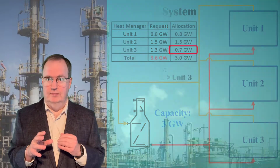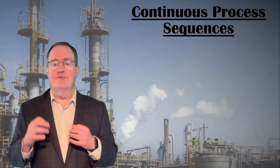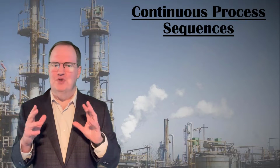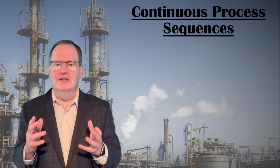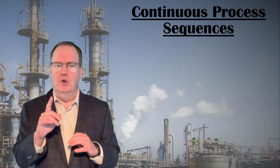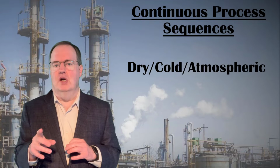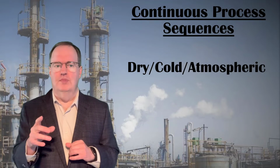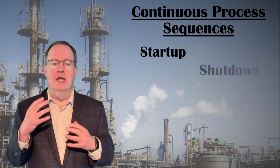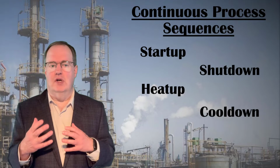The next area where sequential logic is very important is for continuous processes. But you may be saying, continuous processes don't have sequences, they maintain one state in time. Which is true, but only when they're already operating. Every piece of process equipment starts and ends dry and at room temperature and atmospheric pressure. Startup, shutdown, heat up, and cool down procedures all require sequences if automated.